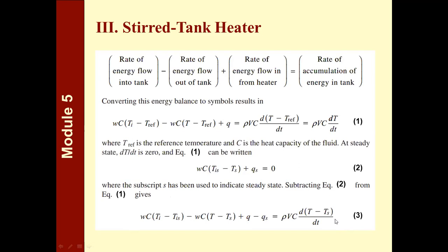Either you assume that there won't be any changes in the amount of heat supplied to the tank, or there won't be any changes in the inlet temperature of the fluid entering your heater. So you can only relate T, the temperature of the fluid inside the tank, to changes in the inlet temperature or changes in the amount of heat introduced into your tank.